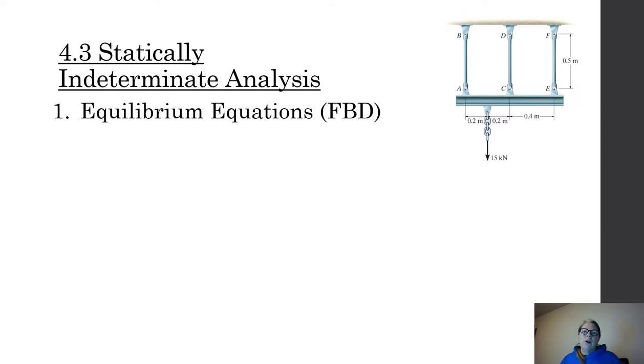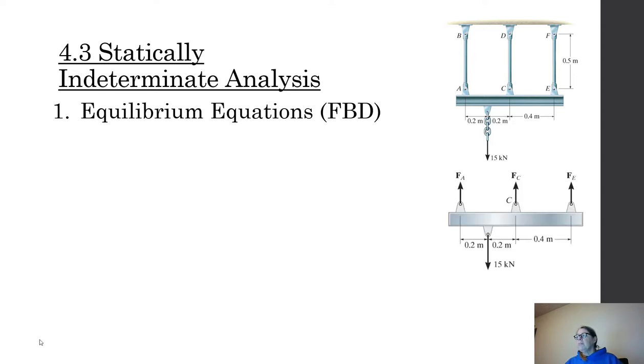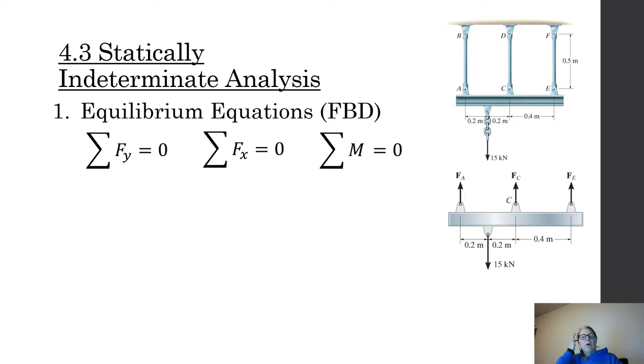So let's walk through what our steps are. This is super important. Let's walk through our steps. Okay. First off, I have to determine, is it determinate or is it indeterminate? Because I don't want to do a bunch of extra work if I can use equilibrium by itself, okay? So the first thing I'm going to do is draw a free body diagram to set up my equilibrium equations. And so when I draw my free body diagram, I'm going to cut those two force members and call them forces because I know they're internal forces. And I can sum forces in the x direction, I can sum forces in the y direction, and I can sum moments about a point.